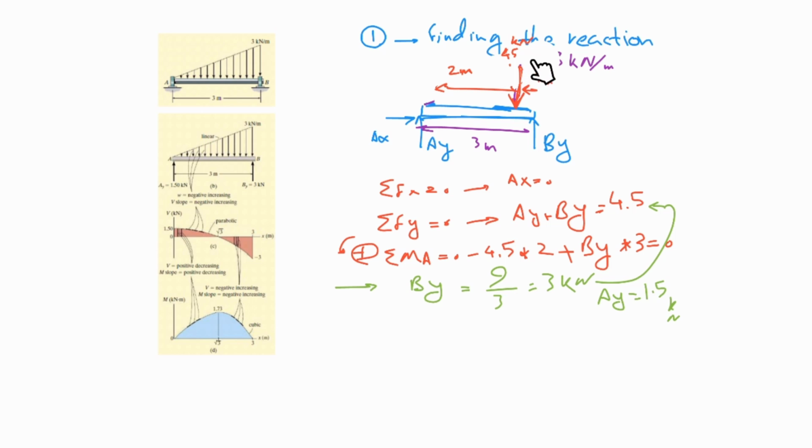I mentioned at the beginning that we need to replace this distributed force with a single force, but at the second step, which is here, you get back to the distributed load. Otherwise, you have changed the problem, meaning that you have removed this and you have this instead of that. We do this for finding the reactions only, not for solving the problem. We found reactions, we are done with this, and this goes, and we get back to the previous problem with reactions. Right now I have these two, which are obtained from this step.